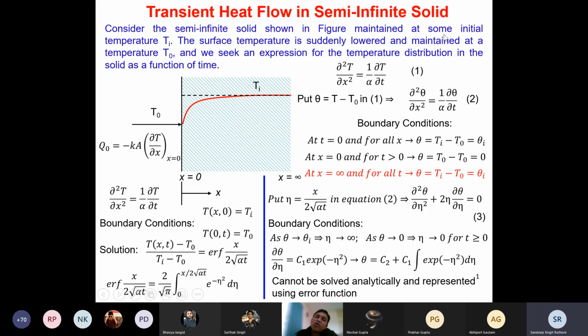Now what will be the typical profile in this case? See, if I put this entire solid in the fluid, then the case is different, in the sense that if I give sufficient time, the temperature inside the solid will also be T0, correct? But here, that uniform temperature profile you will never achieve, because one side is infinite length, isn't it?